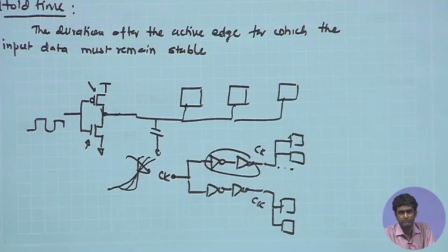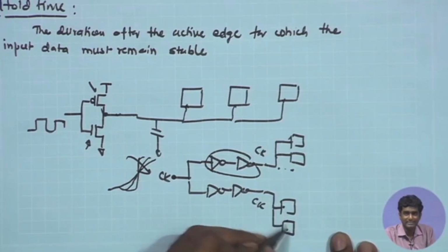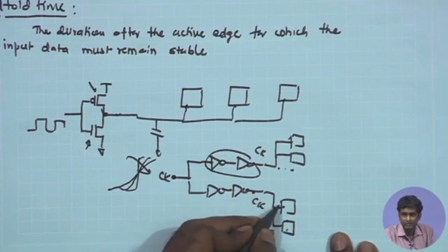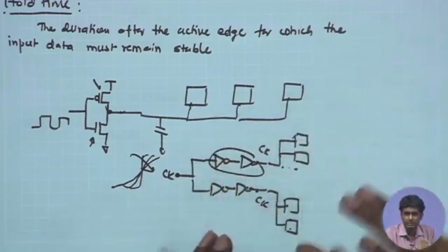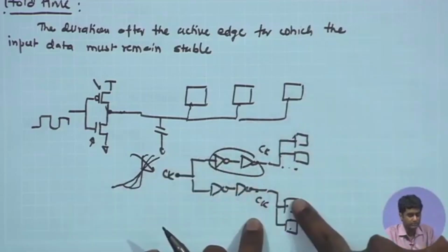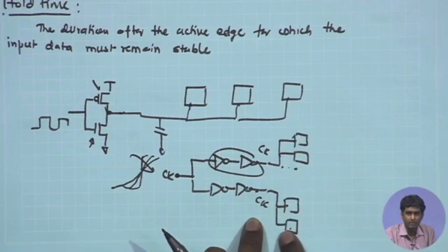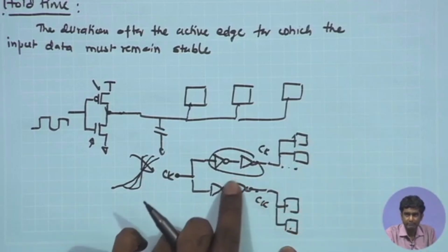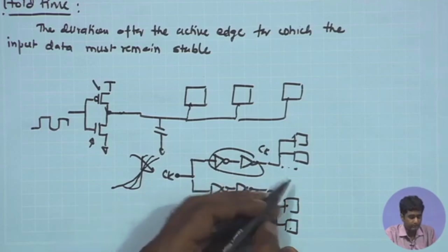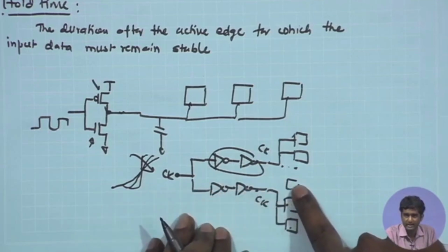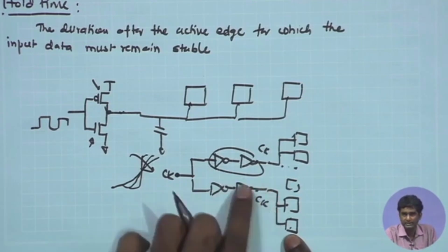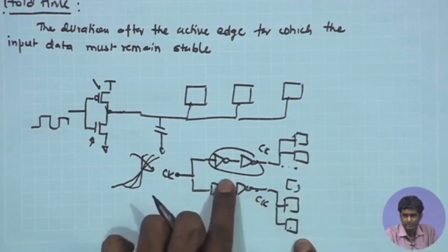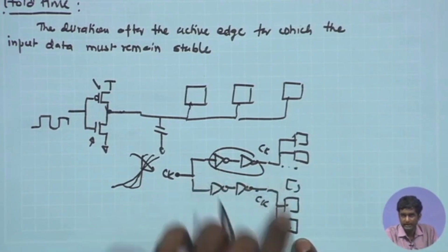But there is an important definition of fan out that comes in digital circuitry, which deals with how many similar gates are driven by a single preceding gate. In terms of analog circuitry, we talk about parasitic capacitances and load, etc. In terms of digital circuitry, because we are dealing with individual gates, we talk about fan out. So, if you have more number of gates being driven by a single gate, the fan out of that gate is large. Here if you have three such logic gates, maybe AND gate or OR gate or NOT gate, being driven by the previous gate, that means the fan out of this gate is 3. If you have n different gates driven by a single gate, the fan out of this gate is n.